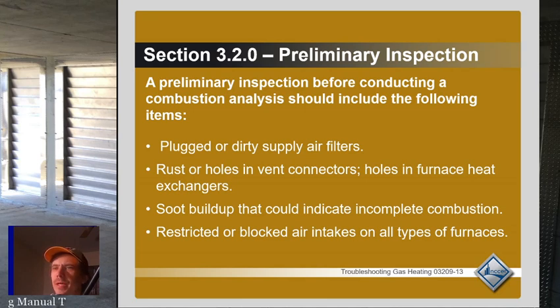It can get extremely dangerous as well, so you always want to inspect any piece of equipment for signs that soot is building up on the inside, because that soot can catch fire as well and cause other issues, and it will block the air intake more, leading to more soot, which is why it tends to snowball into a huge issue. And then restricted or blocked air intakes, you need, again, enough air in the equipment. So a good example is those FVIR, the newer gas water heaters, often have screens at the bottom that can block the air intakes on them, and that will cause issues with combustion.